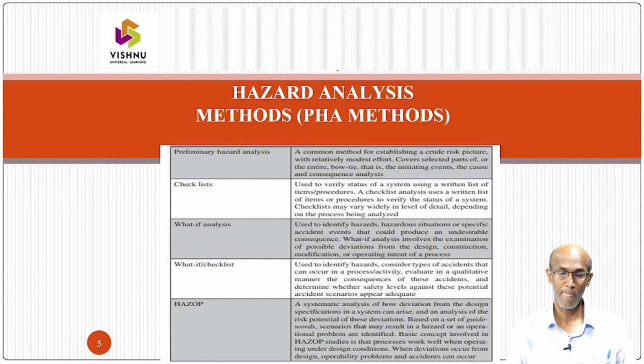What-if analysis is used to identify hazards, hazardous situations, or specific accident events that could produce an undesirable consequence. What-if analysis involves the examination of possible deviations from the design, construction, modification, or operating intent of a process.